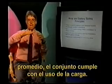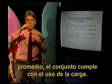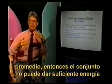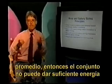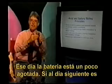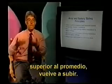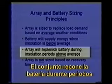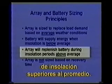If we have an average day, the load usage is met by the array. But if we have days where the insolation is below that average, then the array simply can't give enough energy into the battery to run the load. The battery is slightly depleted that day. The next day, if we have an above average day, it's filled back up. So the array, on the average, replenishes the battery during periods of insolation that are above average.